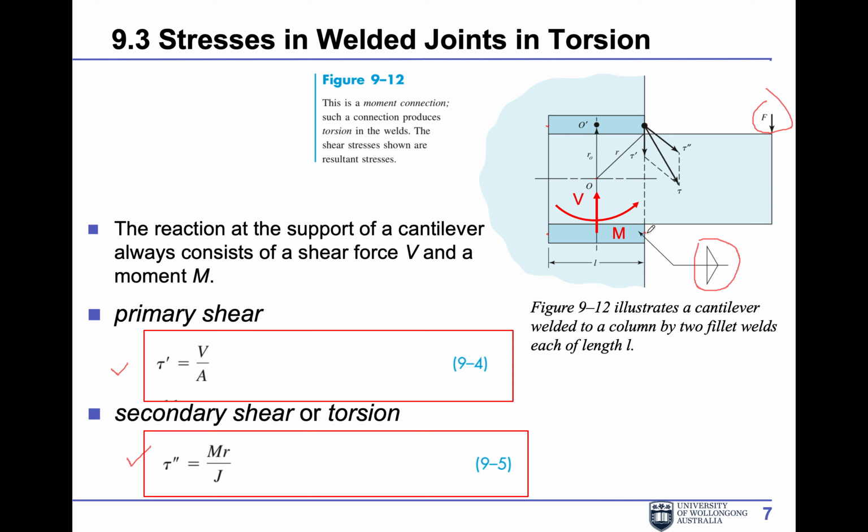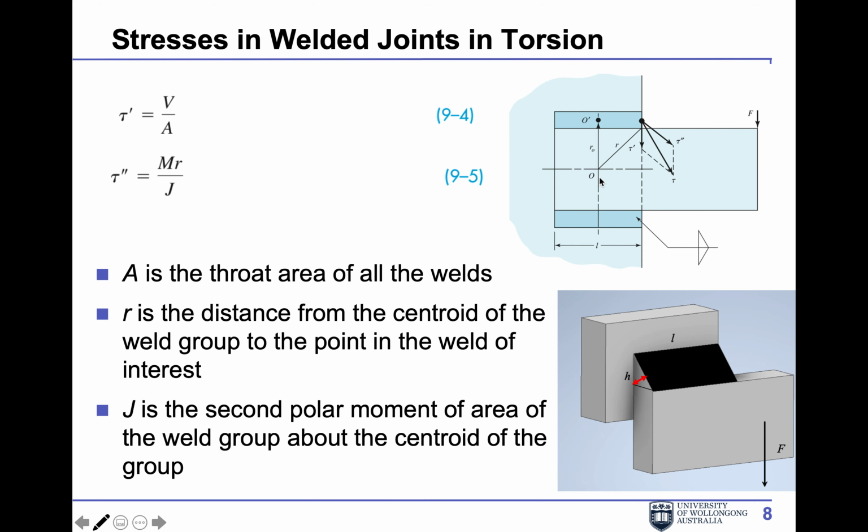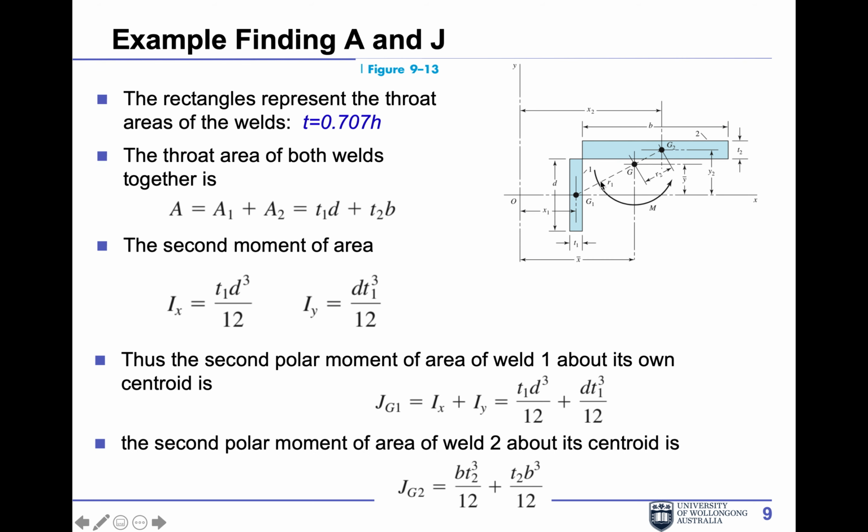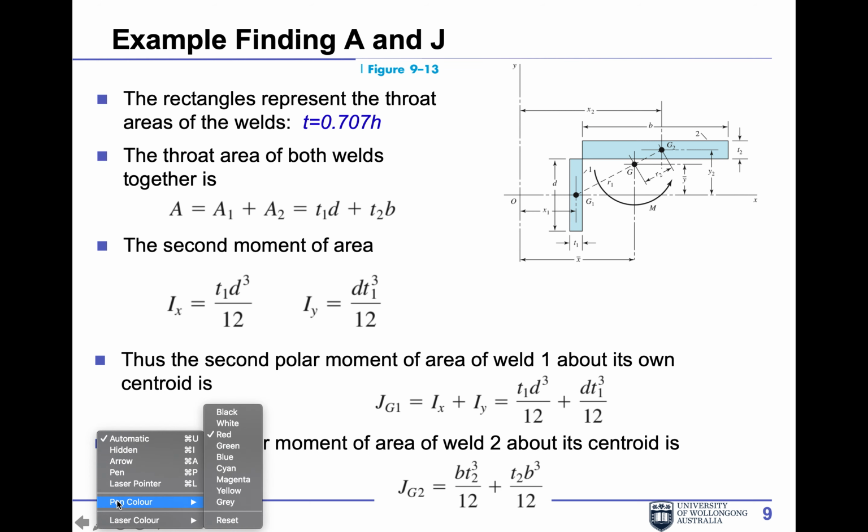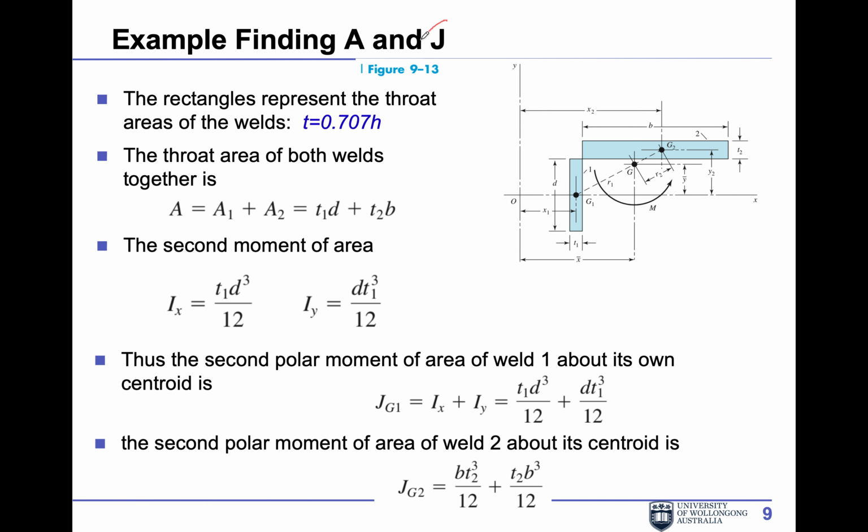locations. And divided by J. So this is kind of the tricky or difficult part. J is the polar moment of inertia. So you can see the whole thing is going to rotate around this in this plane, so the rotating axis goes inside or outside of this screen. Again, to do the calculation, the challenging bit is to calculate the J.